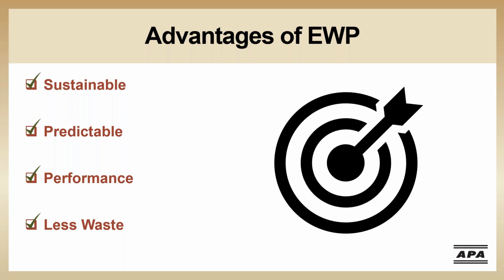And fourth is waste reduction. So the ability to have long lengths and pre-cut framing packages is also going to result in less waste, which impacts the amount of material going to the landfills. And for the contractor, this could also result in reduced disposal costs. When using conventional framing lumber, as much as 10% of primary framing members are rejected due to excessive cupping, splitting, warping, etc.